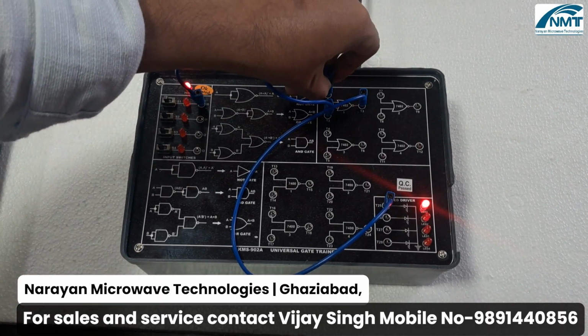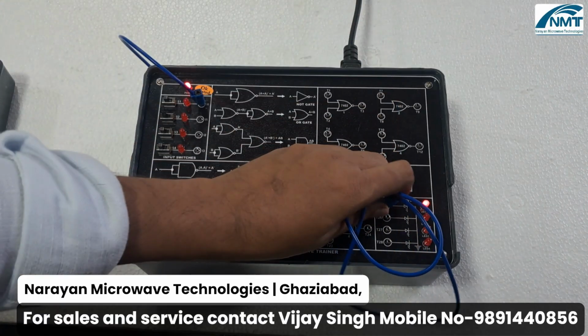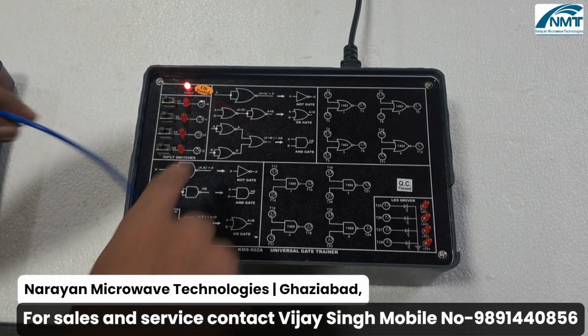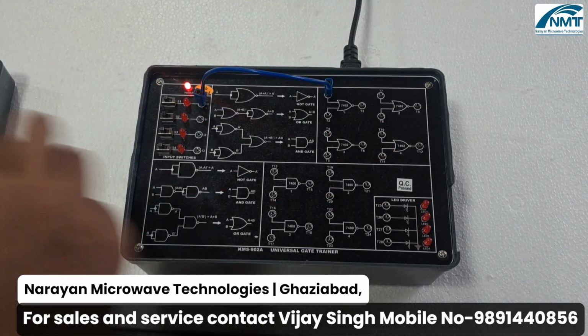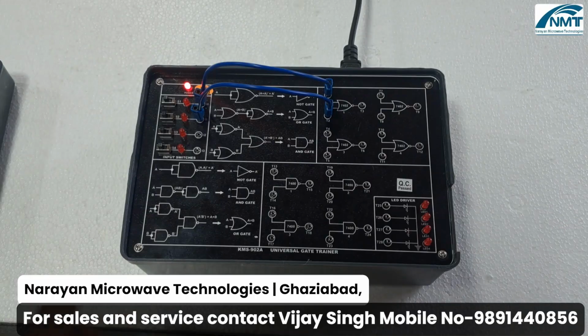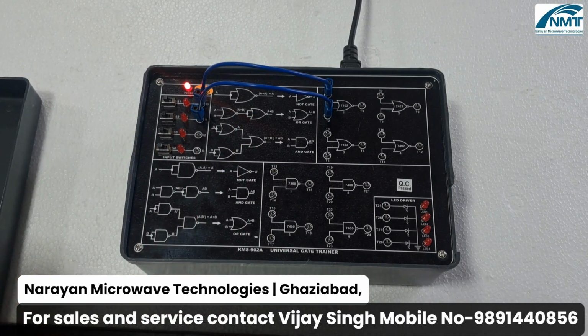Now we can do the experiment of the second logic gate, which is the OR gate. This is the graphical representation for the OR gate. To perform the operation of the OR gate, let's do the connection. A and B are simply given to the inputs of our 7402 IC, which is the NOR gate. Here you have to use one more NOR gate.